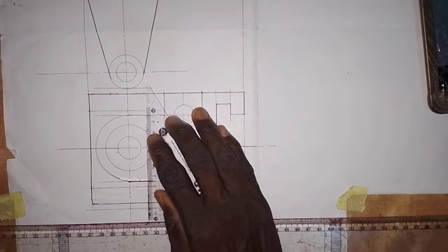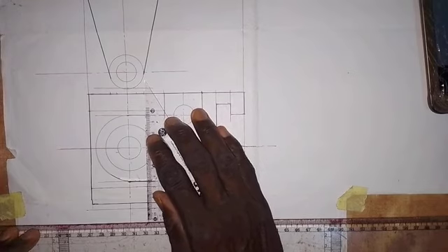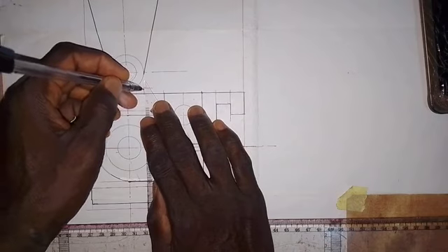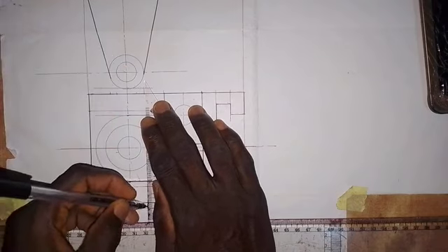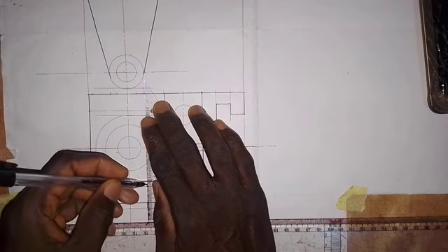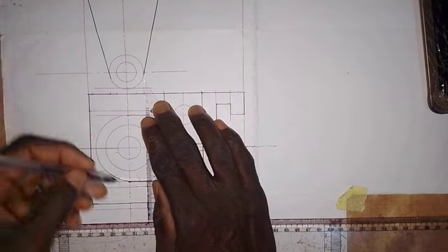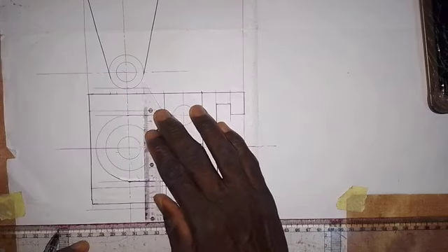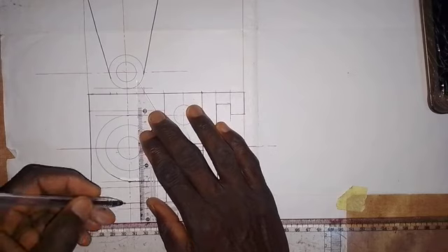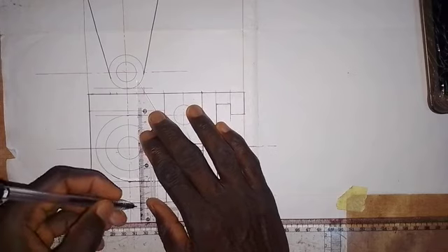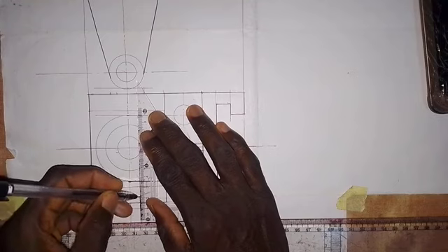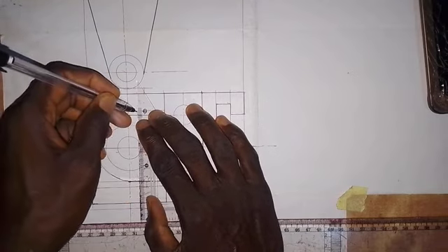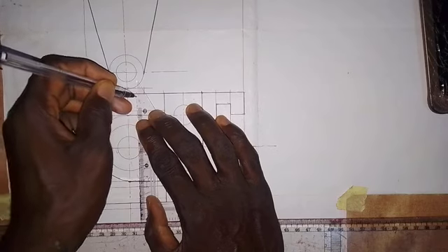Just going to project. For the outer one, just make this a thick line here on this side. That is the only part that we see, and here it will be hidden because it's under the whole body. So here also it will be hidden. It is under the whole of it. While for the inner one, it will be hidden for the whole of that distance, 25 millimeters. So we draw short dashes line here like this, and here we also draw short dashes line to be hidden from us. All right, so we have this.